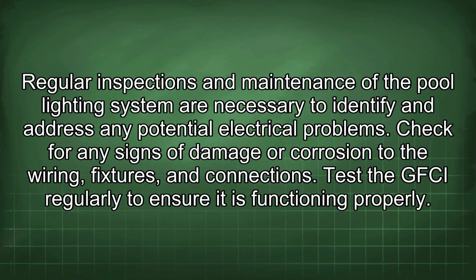Regular inspections and maintenance of the pool lighting system are necessary to identify and address any potential electrical problems. Check for any signs of damage or corrosion to the wiring, fixtures, and connections. Test the GFCI regularly to ensure it is functioning properly.